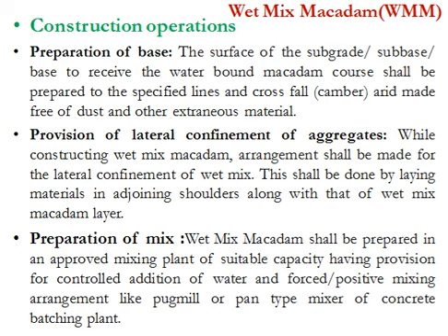So if it is required, water is sprinkled on the subbase, base or subgrade, and after sprinkling with a minimum quantity of water, the layer can be rolled with a roller with one or two passes if it is required.